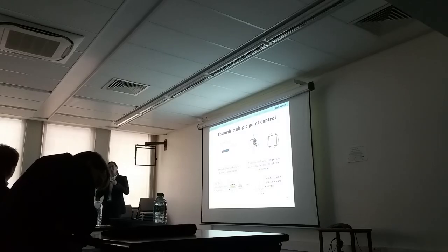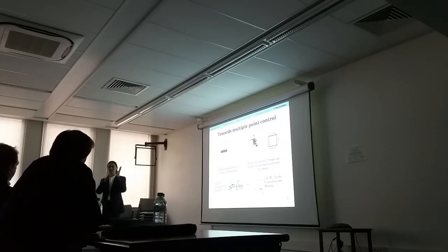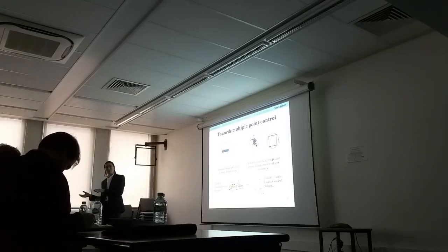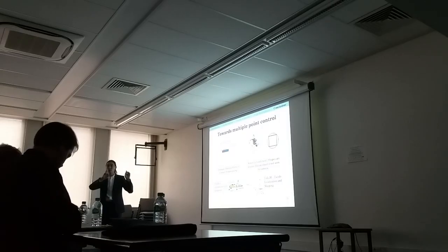Yeah. First of all, we can solve the inverse problem. The BioTac is a cylindrical object, or we can assume spherical, and we assume that the surface is flat, and there is a contact between the spherical tactile sensor and a flat environment. We can sense the center of contact point on the sensor, and by controlling the center of contact inside this tactile array interacting with the environment, we can still apply this tactile servoing framework where we map different features.